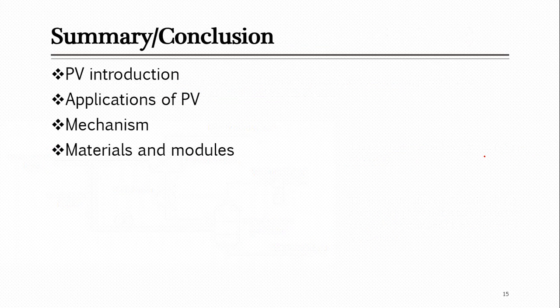So that's it. In this lecture we started with pervaporation. What is pervaporation? Pervaporation is a combination of two words, perm selective and evaporation. Through this membrane, when separation takes place, after permeation the liquid species get converted to vapor on the other side due to the application of vacuum, or very low pressure compared to ambient pressure.